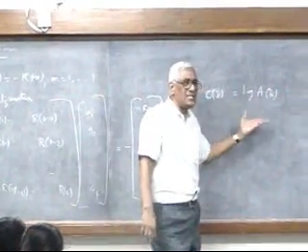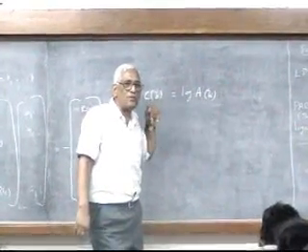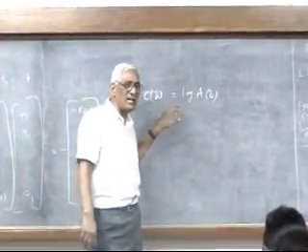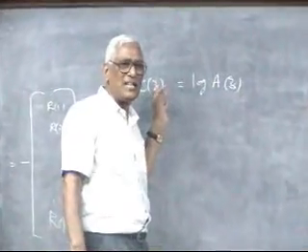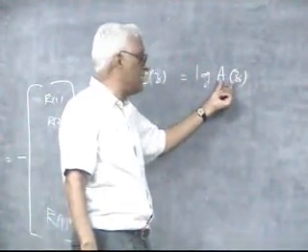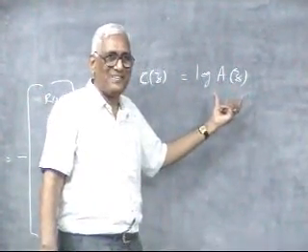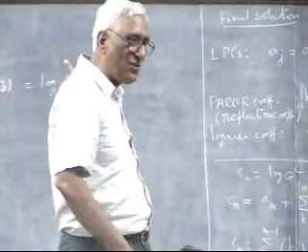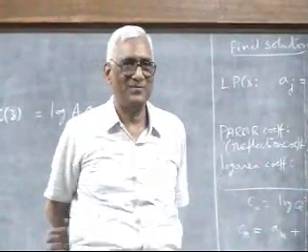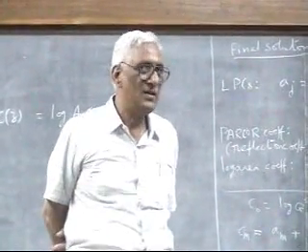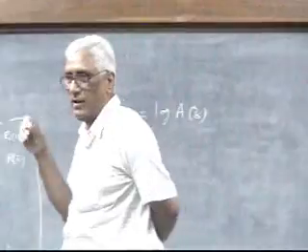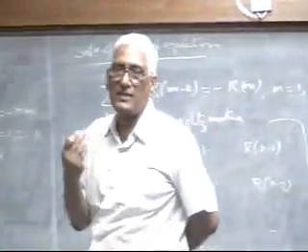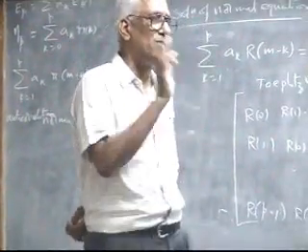If my Z is e to the power of j omega, I am evaluating it on the unit circle. So whichever way you want to look at it, if I just take the specific case of Z equal to e to the power of j omega and take a minus here, that is nothing but the spectrum of this, and the log spectrum of that, I am taking the inverse of that. So that is the coefficients of this. See the problem here, you have to stretch your imagination, otherwise if I give the solution now, you only note down that.